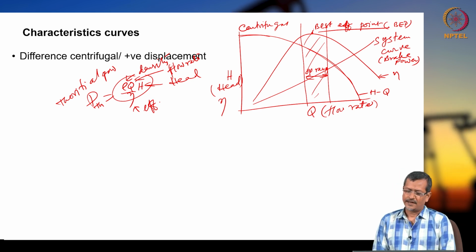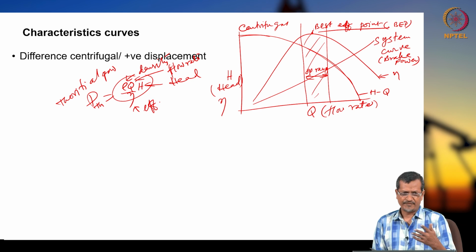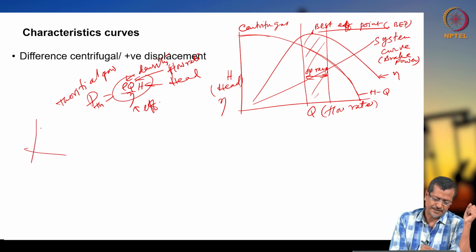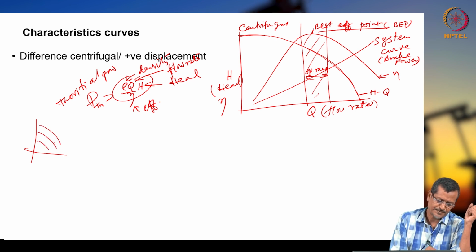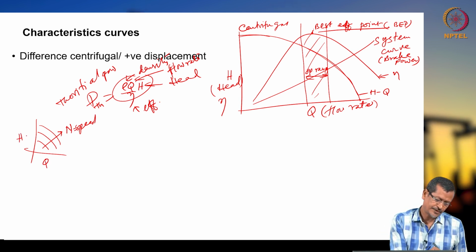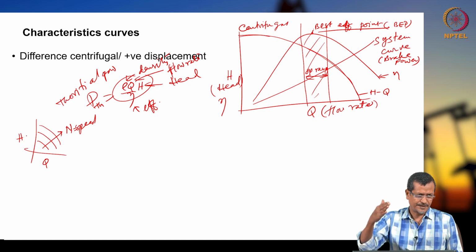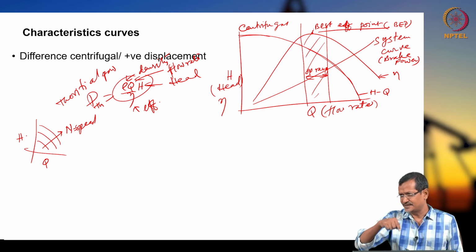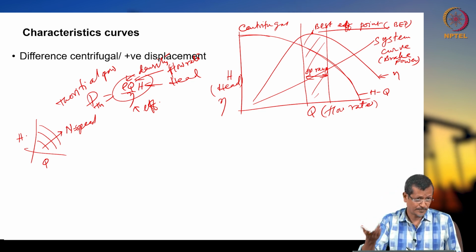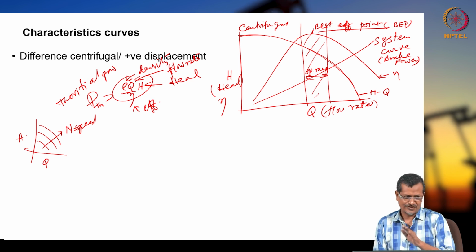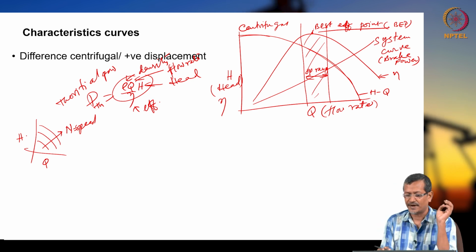And if you have a VFD, what will VFD do? If you change the speed, my HQ curve will change like this. So if you are increasing speed, head and Q will be increasing. When you are increasing speed, your energy consumption also will be increasing. So every pump will have its optimal speed range. The company will be providing this. This is called pump characteristic curves.